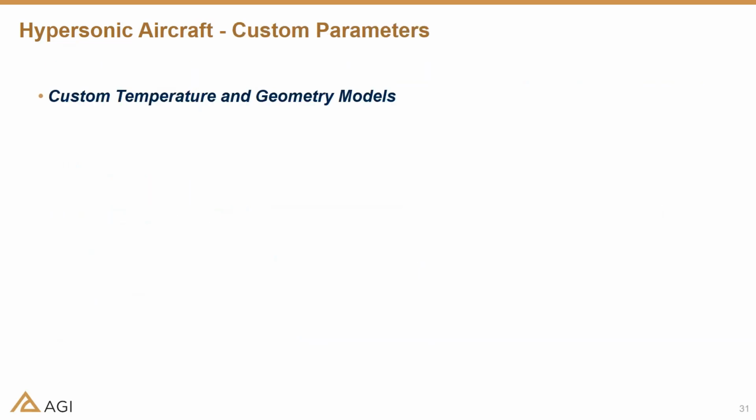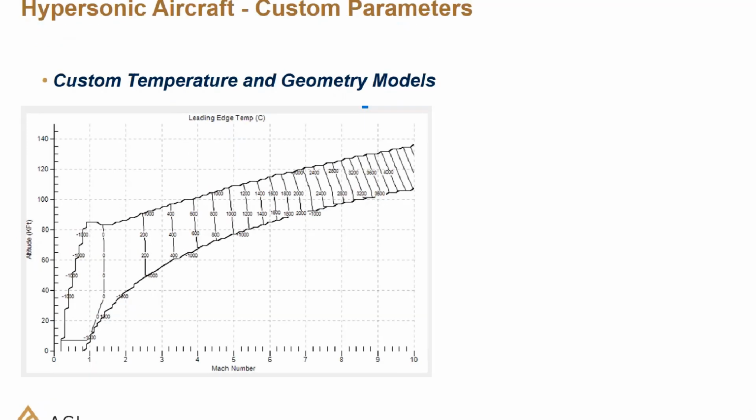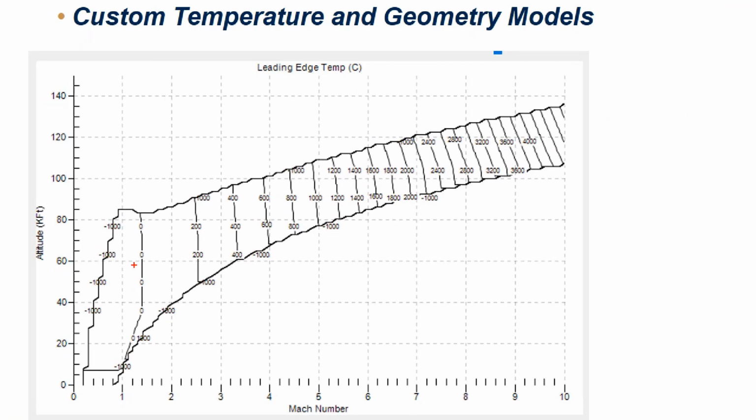And then if we go to the next slide, that left-hand slide comes off of our aerodynamic model, and it's showing you what we call the stagnation temperature, the total temperature of the wing at that flight condition, using thermodynamic properties in the atmospheric model. And as you can see, or hopefully you can see, and I can't see too well because I have old eyes, but if you get up into the Mach 9 regions, you start seeing temperatures that are over 3,000 degrees.